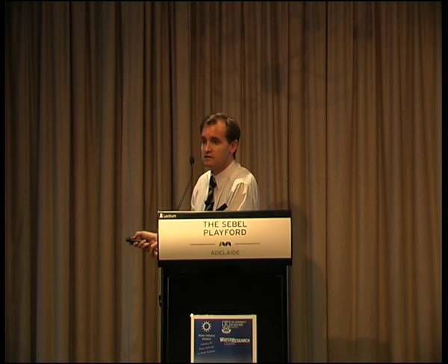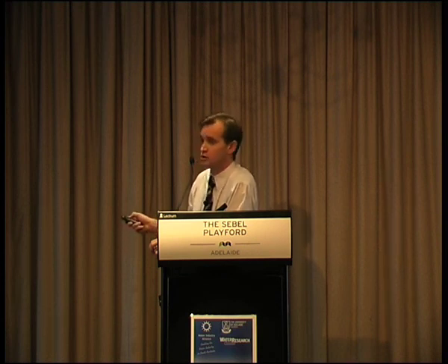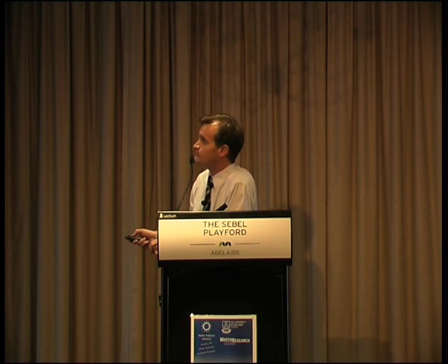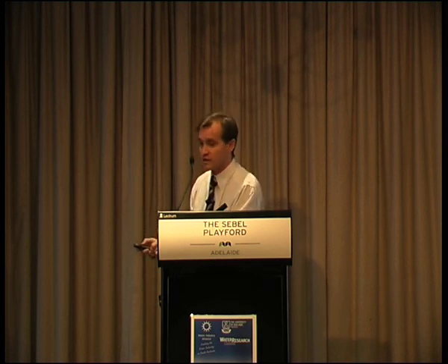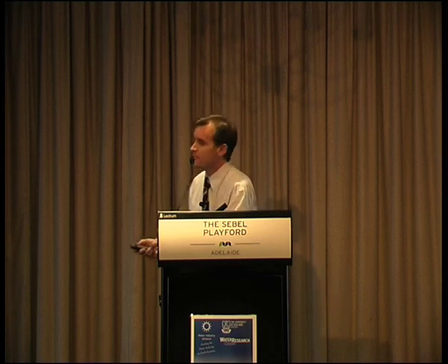The key element of this overhead is energy. That is what is required to make this process possible. And it's required mainly for pressurising the seawater for reverse osmosis to occur. But it's also required in other components of the process: pumping the seawater, pre-treatment, energy recovery, post-treatment, and storage and distribution. Now this is important because energy is the dominant factor in operating costs for seawater desalting.